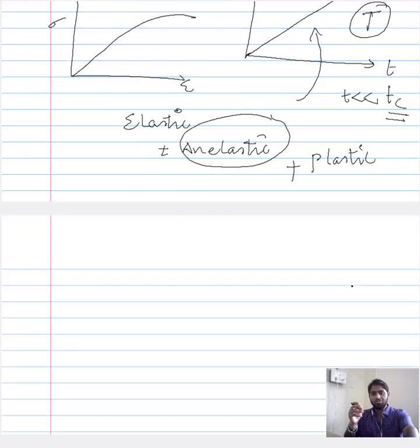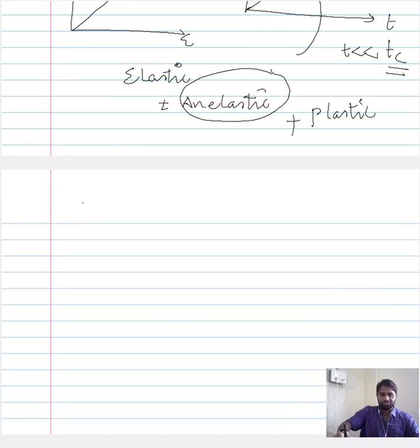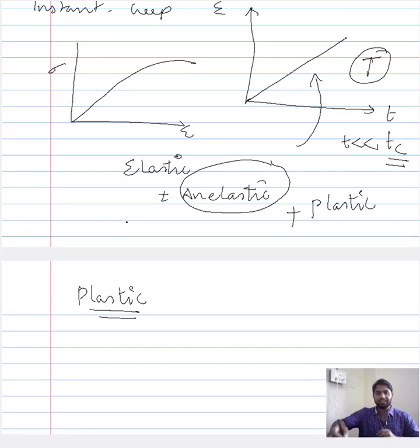Now, once your deformation is governed by the plastic region, and by plastic deformation I mean, once you initialize the plastic deformation, we can talk about it in terms of dislocation. Once the dislocations nucleate and the existing dislocations begin to multiply, you move away from the elastic region in the regular stress strain curve and move into the inelastic or the plastic region.